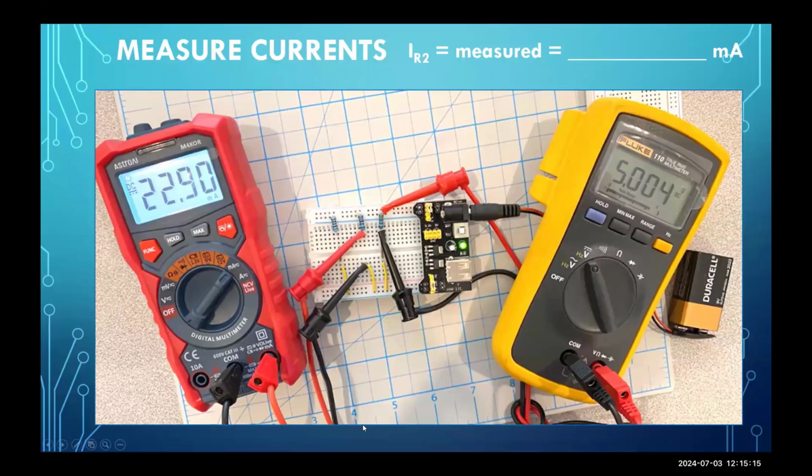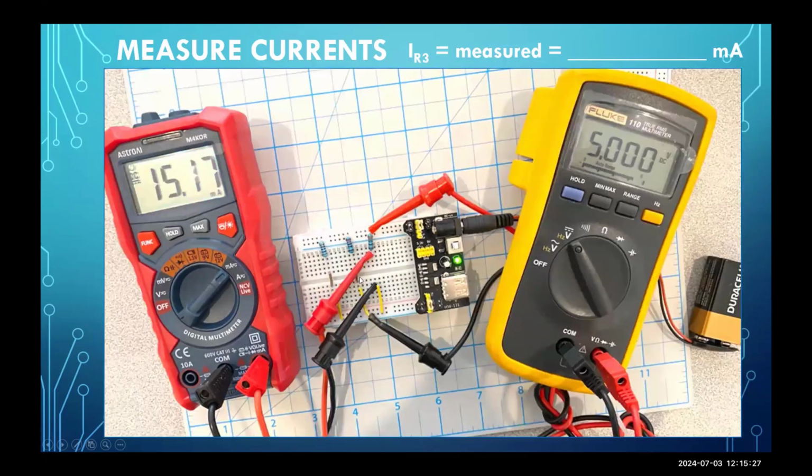Now, next, in order to measure the third branch current, I need to rebuild the second branch and then pull out this last jumper to create an open on the last branch. Take a look. Are my first and second jumpers in place? Is my third jumper, and only the third jumper, removed?